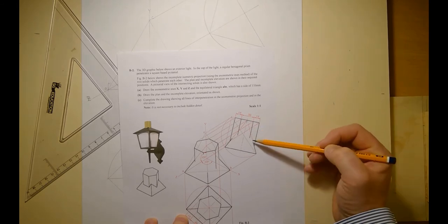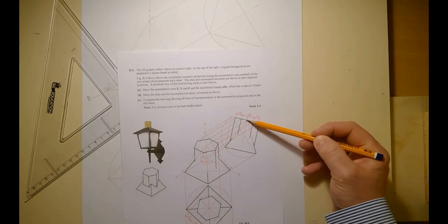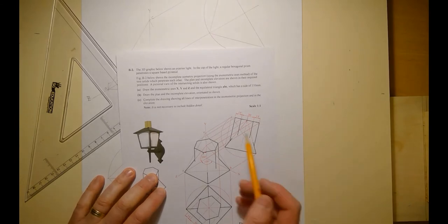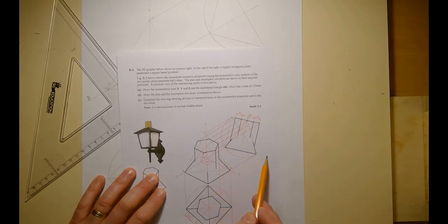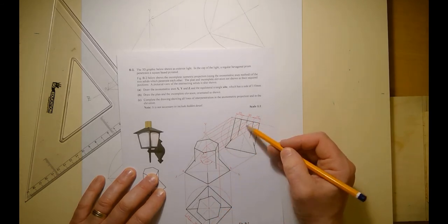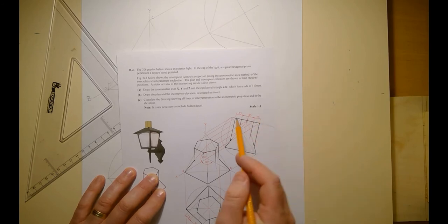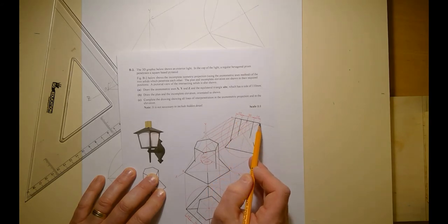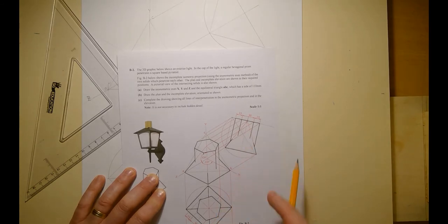Okay, so we want to deal with this point here where the pyramid goes up to, and it's in the very center of our hexagonal prism. We're also given a little clue that this is in line. Here's a little projection line that will show the top of that is in line if we were to go out here in the same basic direction as this. The top of that is in line with the bottom of that, and this here is our center line to show that this point is in the center of this line. So we just project 90 degrees to that line, and we'll get that point by going straight across from here. After that, it is simple enough. This is 30 wide, it's all centered, so this is 15 and 15, and this is 15 and 15.